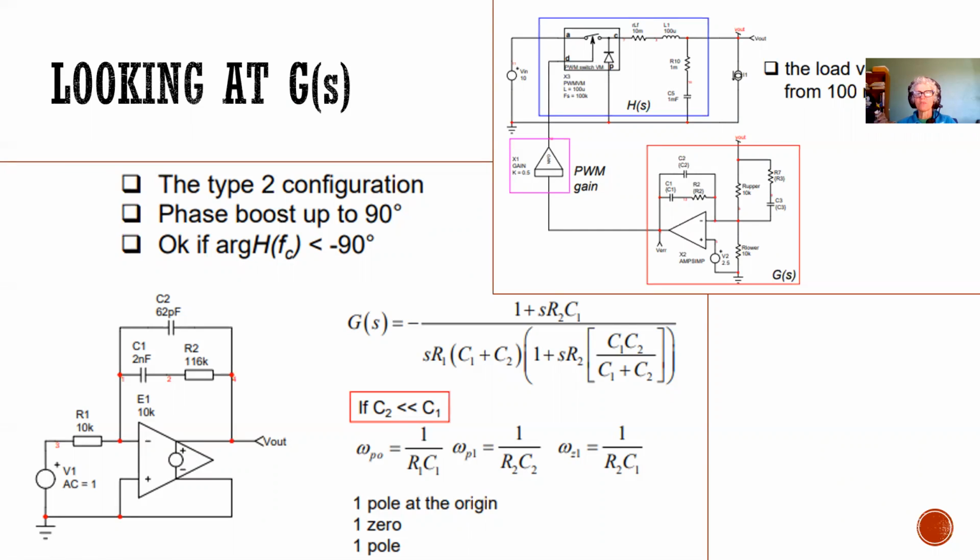I'm going to go back over these slides because I have my own questions now about the slides. But by adding an extra pole and an extra 0, you can actually play with the dominant and secondary poles in strategic ways. So you could keep the bandwidth wide, but you can kind of fend off the 180 degrees phase shift for later.